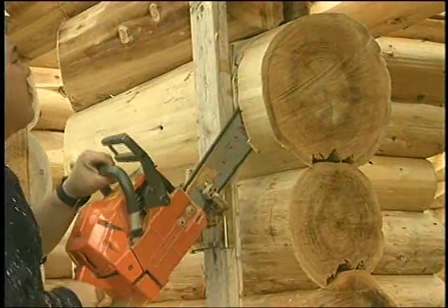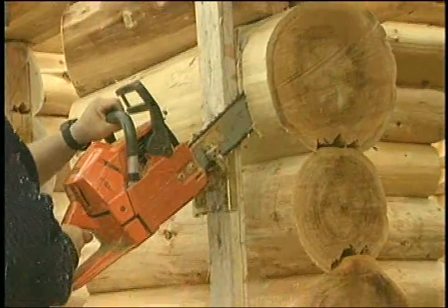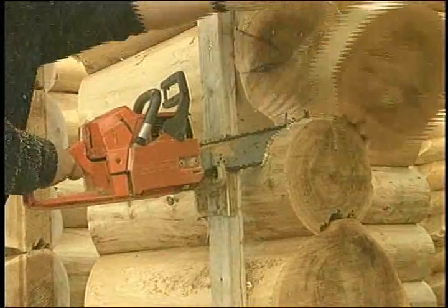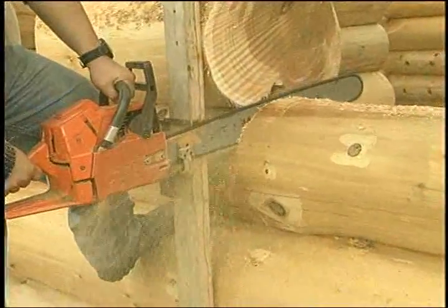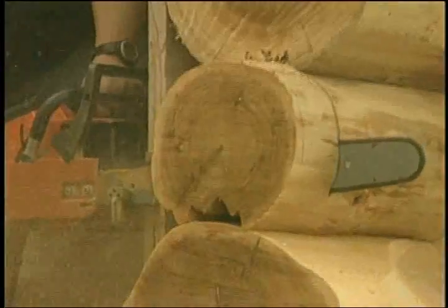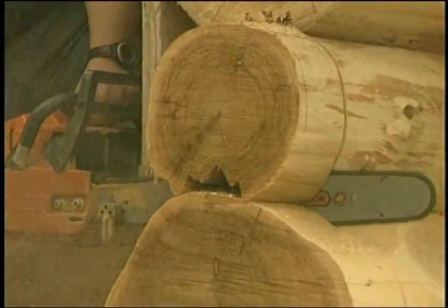Cut the sides of the opening to the final dimension. Use a saw guide or a padded saw to make the cut. Be sure that the guide plank is wedged into line with the center line of the wall so that you're getting a cut at right angles to the wall. Cut to within 1/4 inch or 6 millimeters of the bottom line on each side. Plunge cut through on the bottom line and finish the flat. Then use a level to mark in the cut lines for the keyway.